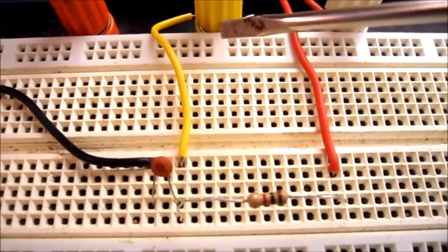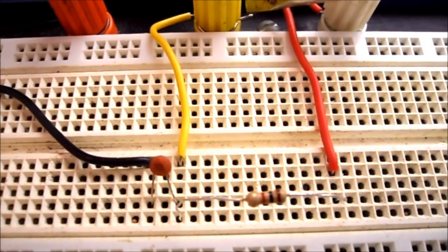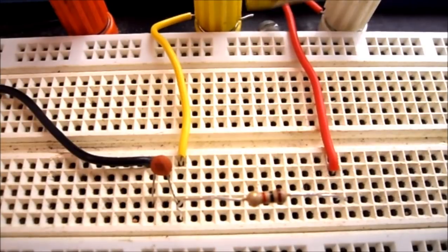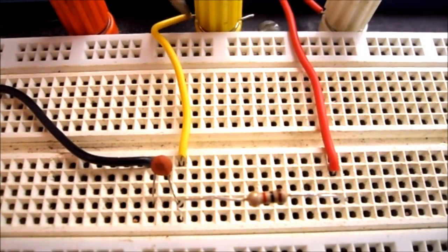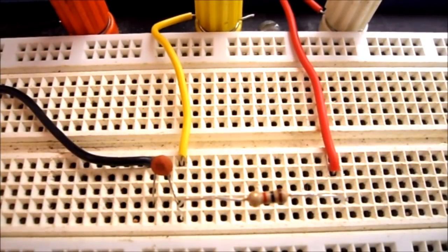I just want to show everybody that coming out of that yellow terminal, you can see the wire pokes out on the other side, and I have a bit of bare wire on this side. Same thing with my red terminal, same thing with my orange terminal. I always leave a little bit of wire exposed so that I can see I've got good metal on metal contact.